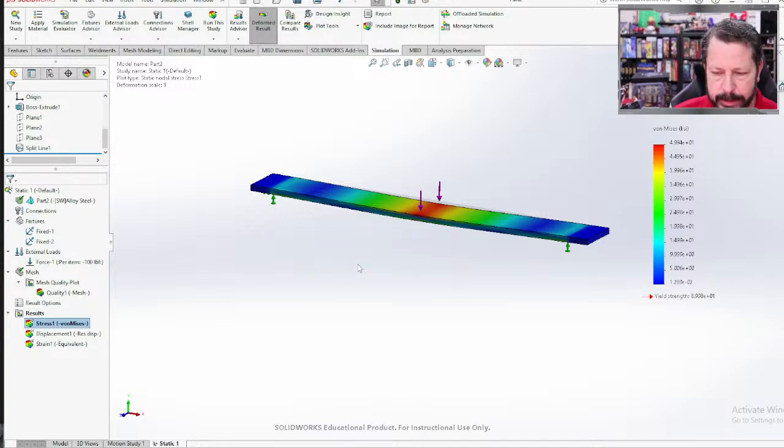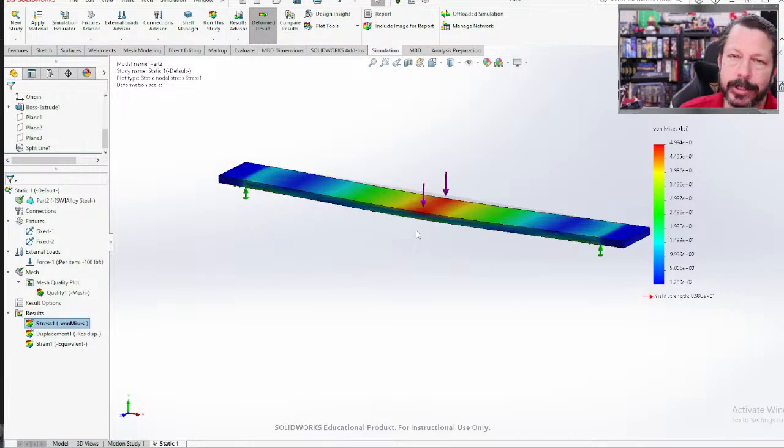I would have thought it would. Oh, you know what? It could have been a compressive stress was maximum, and I've kind of negated the compressive stress. I think this is what's happening. I'm not 100% sure. I think what is happening here, where we had 67 KSI when we had it fixed as a roller, versus 50 KSI when we have it fixed, I think this is not a real thing. I think this is an effect you get when we applied this load.